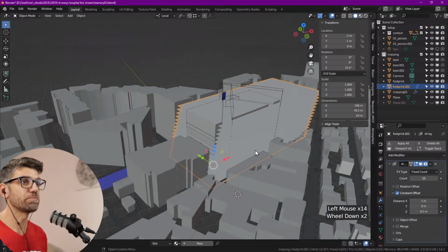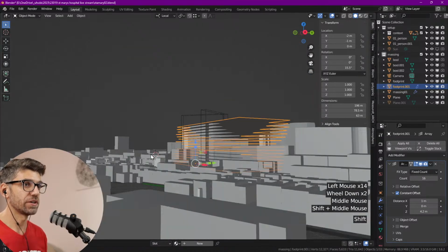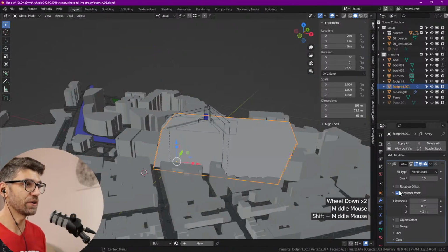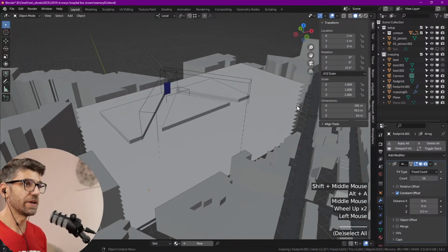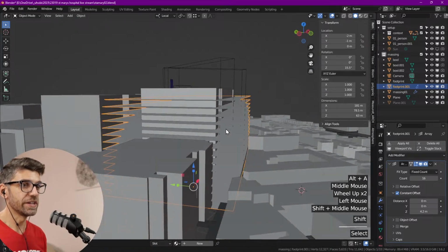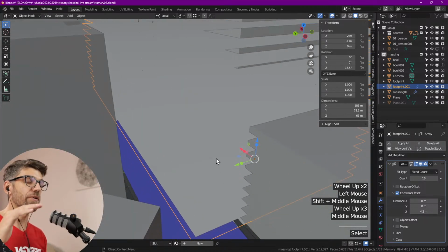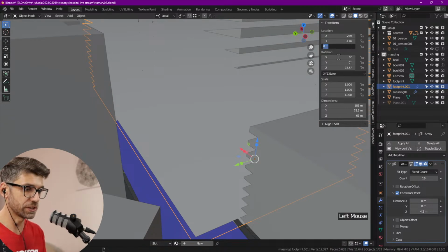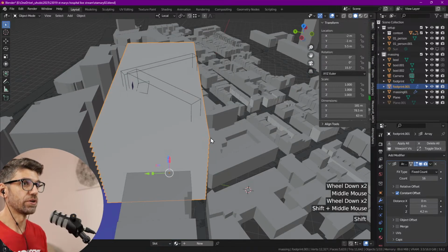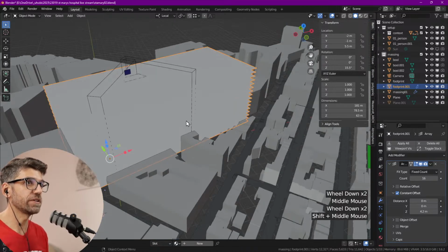And what we're going to do is boolean these floors. And why are they going sideways? Because when you enable constant, there is a default distance x that we just need to put back to 0. Great. Right, so once we have these floors, what I like to do is move them up, because the ground plane, the ground floor, is going to be a little bit more generous. Maybe we do something like 6 meters in there, or 5.5 meters. So that ground plane is going to be something different. These are only the floors that are happening on top.